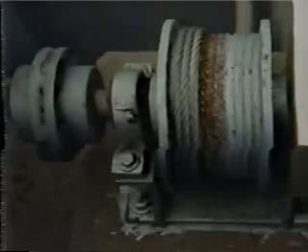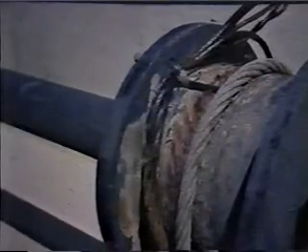If hoist cables are used, see that there are at least 2 full wraps of the hoist cable around the drum when the gate is closed. These are called dead wraps. Here is a drum with insufficient wraps of the hoist cable. The cable has pulled through the U-bolt clamp and frayed.